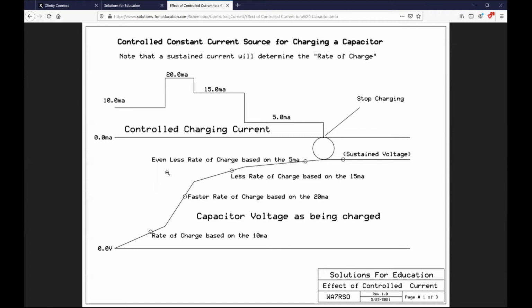Did you know that when electrolytic capacitors of this nature are first made, they are not a capacitor? They're actually a resistor. What happens is you take, let's say, two aluminum foils and wrap them around each other, but you have a liquid electrolyte inside between these metallic surfaces. Then what you do is, that is a conductive material.